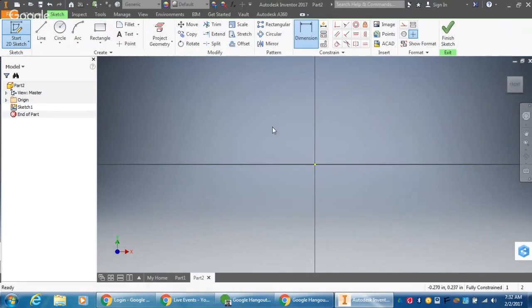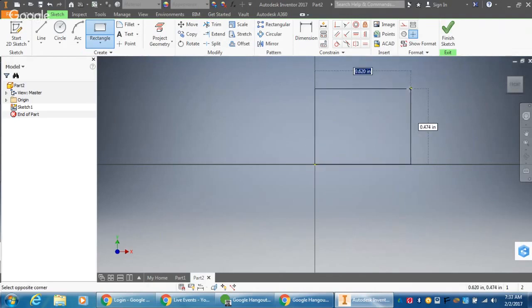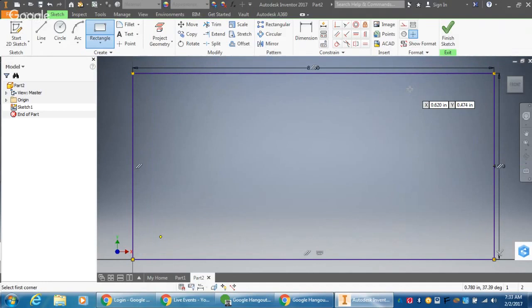We're going to grab the 2-point rectangle to try to figure out what size this is. I'm going to start on the origin, dragging up in the positive X, positive Y direction. And this part right here needs to be 8, tab, 4, enter, home. There we go. So remember tab, just that tab key on the keyboard. All right, so 8, tab, 4, enter, home.